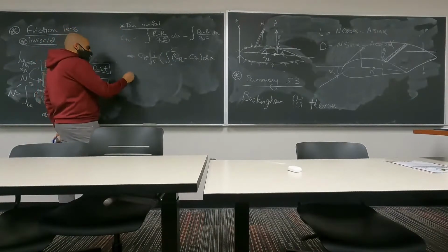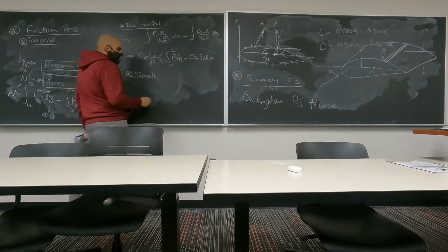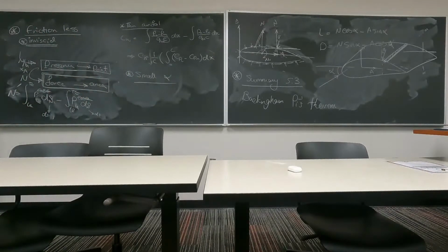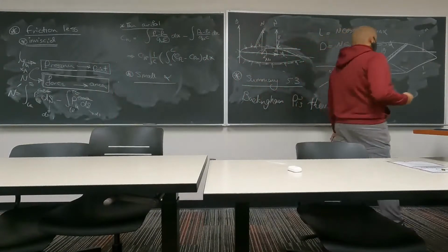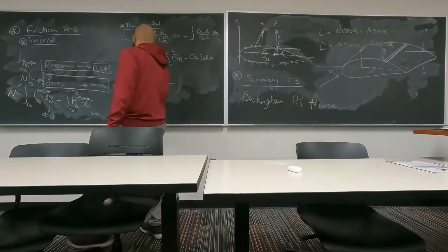For what will happen, how can we calculate the lift coefficient using this normal force coefficient for small angles of attack? Exactly. So when you're dealing with small angles of attack, normal force and lift force are essentially going to be the same. Same is true for axial force and drag force.